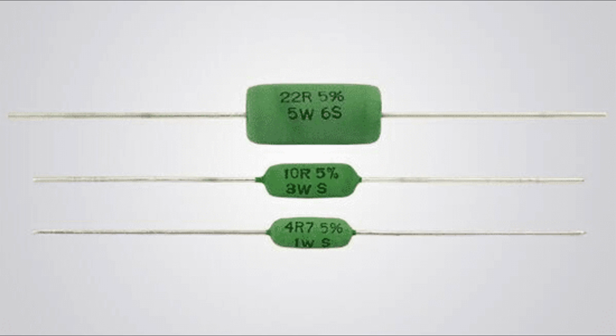Matching resistors. In some applications, it is essential to use resistors with the same or very close tolerance values to ensure balanced circuit operation. This is common in circuits like operational amplifier, op-amp, precision amplifiers and Wheatstone bridge configurations. Test equipment calibration. In calibration and measurement applications, resistors with tight tolerance values are often used to maintain the accuracy of test equipment.